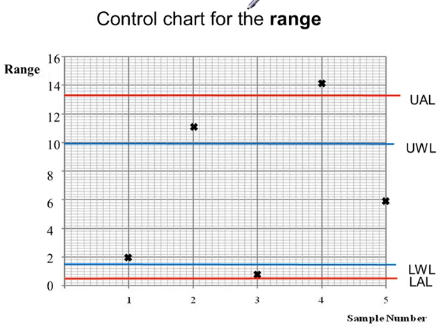And here's a control chart for variability. This time we're looking at the range as a measure of variability in the process, and again for values which fall within the warning limits, everything's fine. Values which fall in between the warning and action limits, we should take another sample immediately. So this one here is showing that the range is getting larger, so something might be about to go wrong here. This one here, again, it's between the warning and action limits. It's a smaller value, it's at the lower end, and we should take another sample again here with the aim of maintaining an improved process.